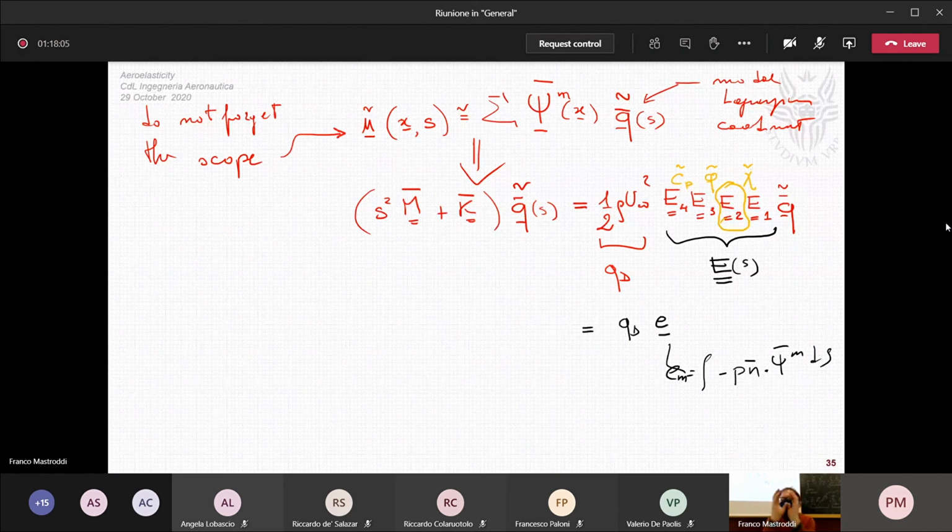So we focused on one specific part of the aerodynamic operator, the potential part, transforming the wall boundary condition into the velocity potential field in the panel. We will describe other steps like the transformation.